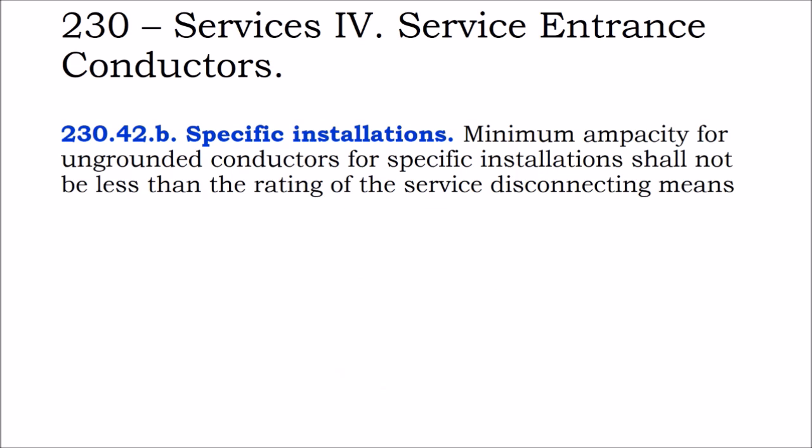The minimum ampacity for ungrounded conductors for specific installations shall not be less than the rating of the service disconnecting means. So, basically if you have a 200 amp electric service, the ungrounded conductors for...